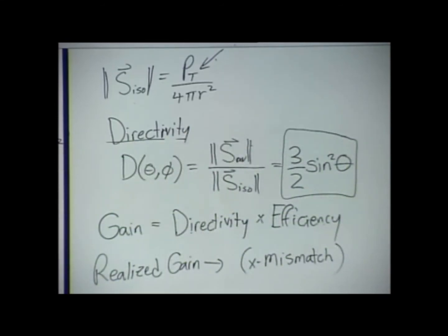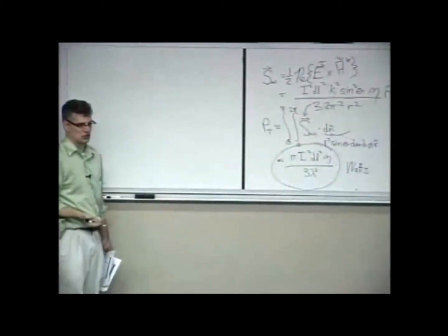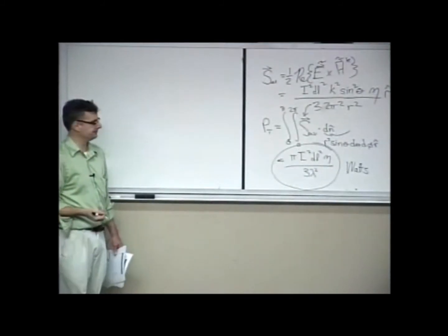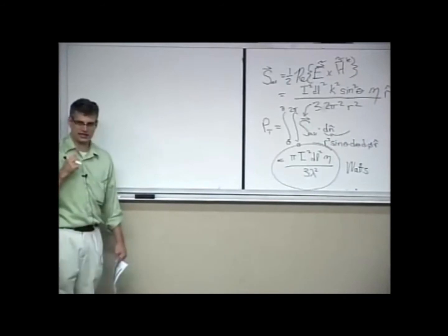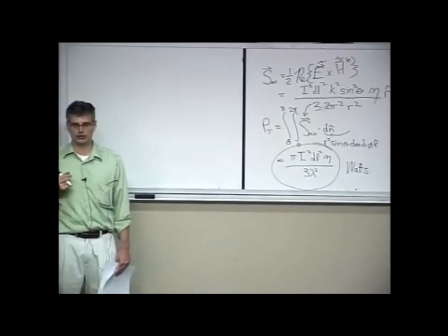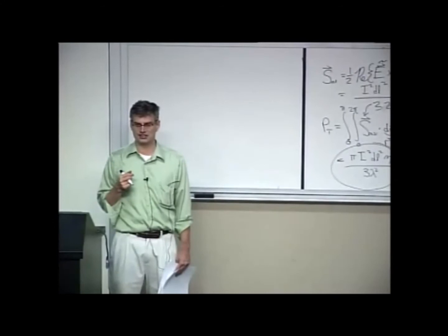Now, I mentioned the idea of an impedance. This still is kind of important because you need to know electrically how to interface your circuit to an antenna. So hopefully you'll be able to know whether or not this thing needs a matching circuit or not. And it turns out we actually have enough information to calculate what the radiation resistance is in this antenna, what it will look like in a circuit.